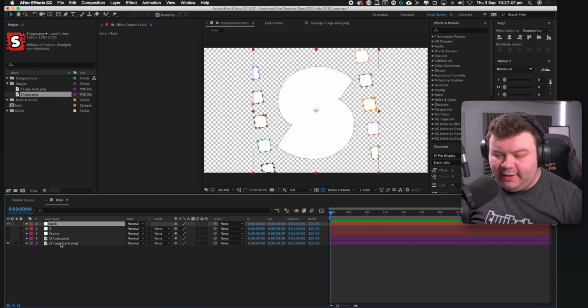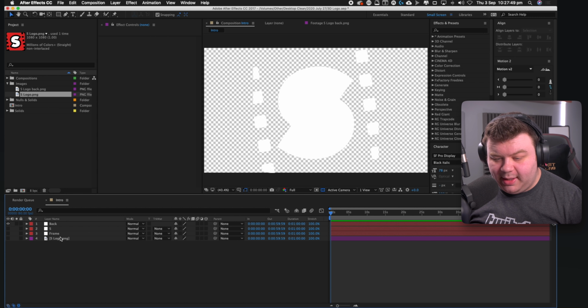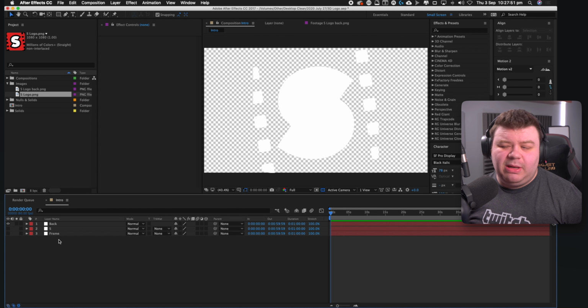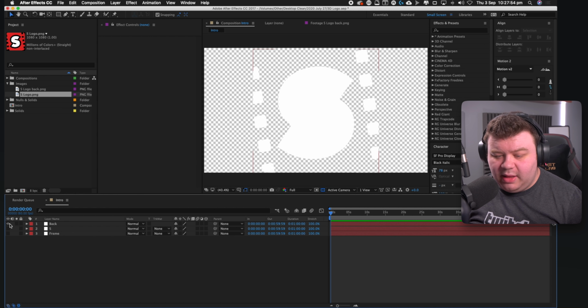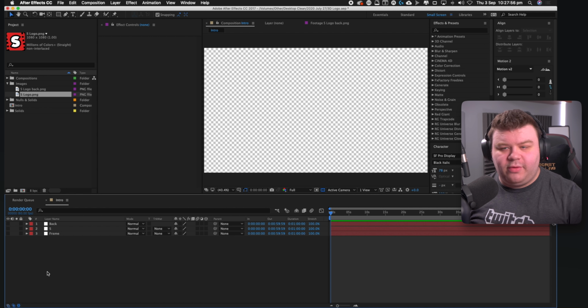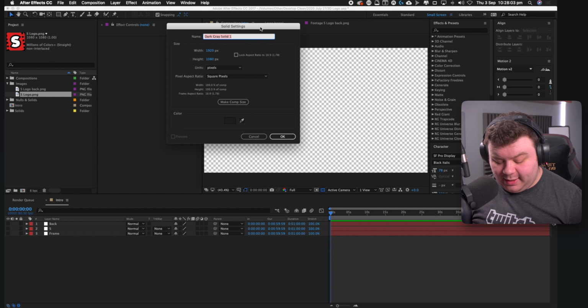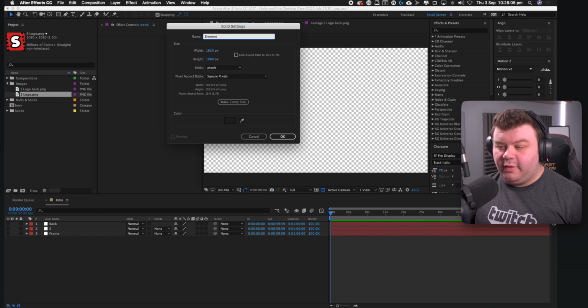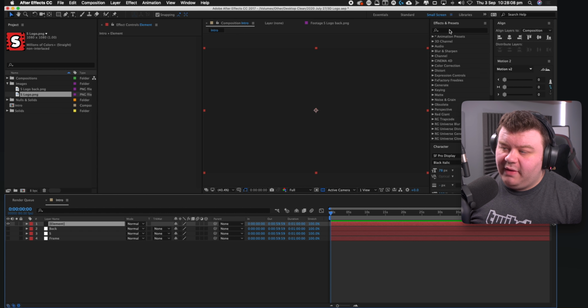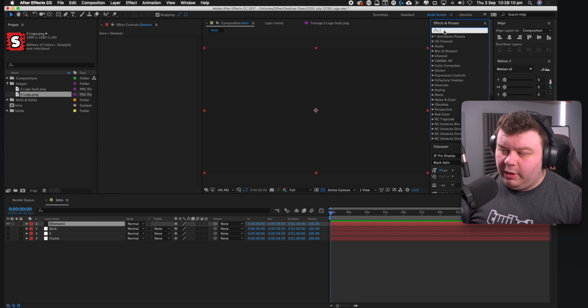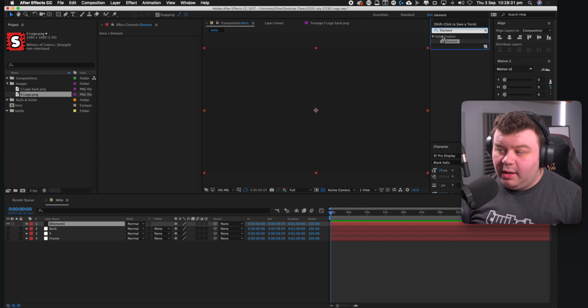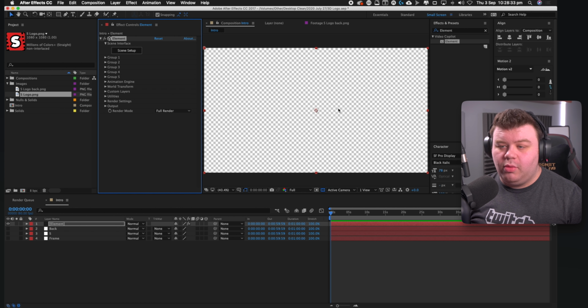And then what I'm going to do is actually delete the original logo copies. So the original PNGs I have here, we don't need them anymore. They served their purpose. We can get rid of them. And then for now, I'm going to hide all the layers just so they're out of our view. And then I'm going to create a new solid. I'm going to layer, new solid. And this one's going to be our Element 3D layer. So just call this one Element, like so. Click OK. And then over in the effects and presets area right here, I'm going to type in Element, like so, and I'm going to double click it to load it into that solid.